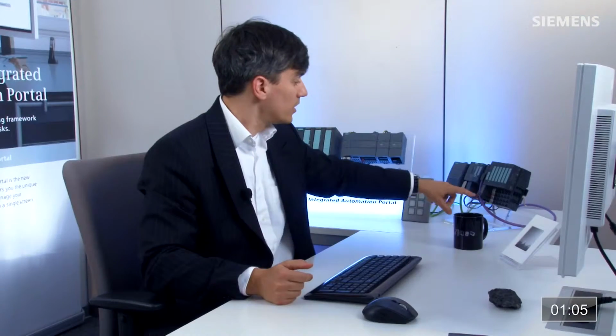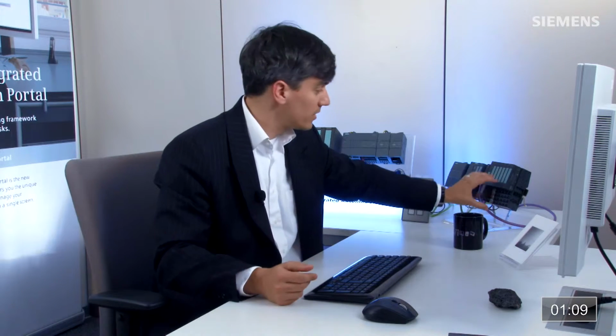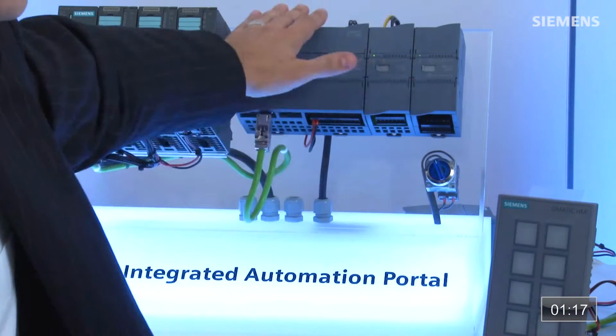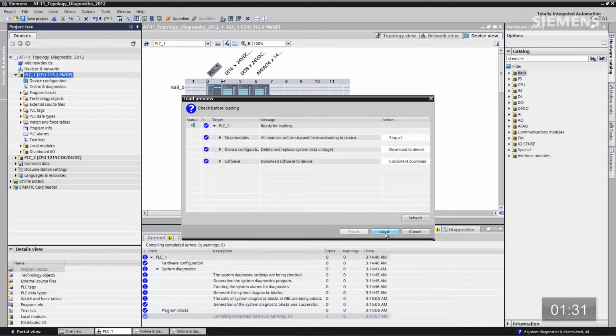So ultimately, if you look at the automation architecture over here, we can generate diagnostics for the channel layer. So let's say, for instance, a wire break to a module failure. We could even have an entire rack failure or another physical layer diagnostic, including HMI and even the master. Any kind of diagnostic can be automatically generated, and you don't have to write one line of code to achieve this. Also, at the exact same time, all the partner port connections on Profinet are also going to be compiled as well.